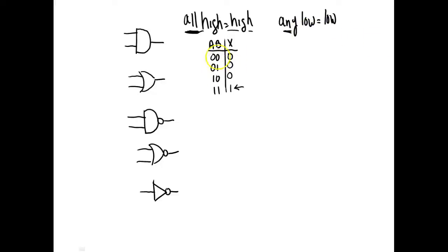So y'all see, this is any low right here. A lot of people want to call that all lows, but if you do that, I'm going to correct you. That is not an all, that is an any. Why is it an any? Because the all is the unique. Which of this truth table, what is unique? The zeros are not unique, right? You understand? What's unique is the one. That's your alls, right? So when we say unique, we mean if we only have one output that gives us that. And that's when we use the term all. But for some reason, people want to call that an all, but that's not an all, it's an any low. Y'all understand that? Very important concept.